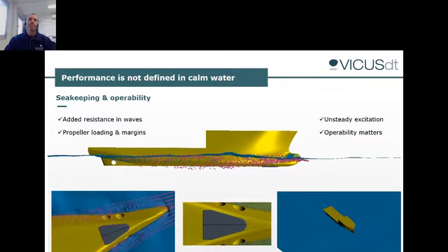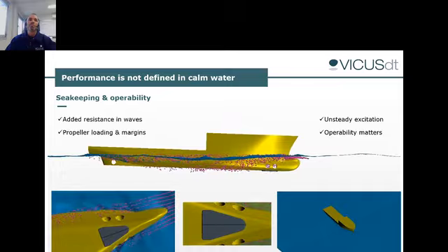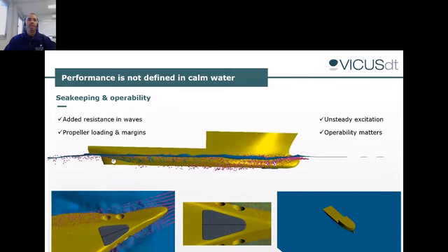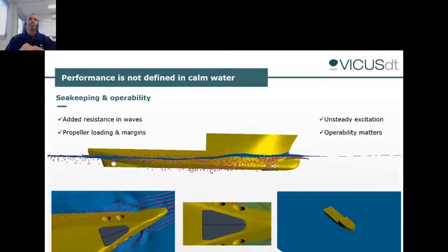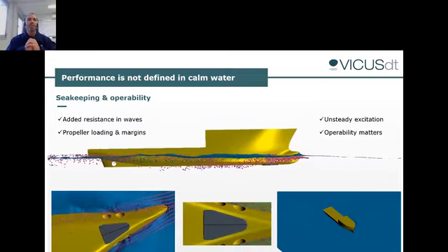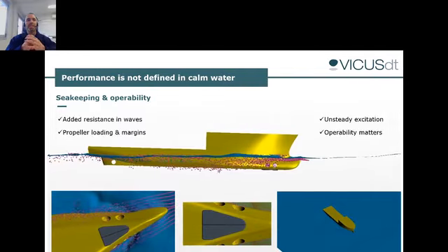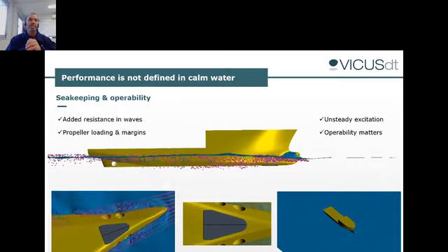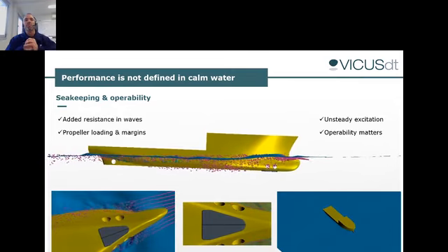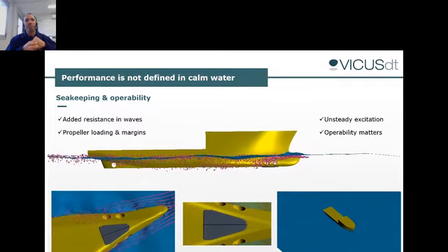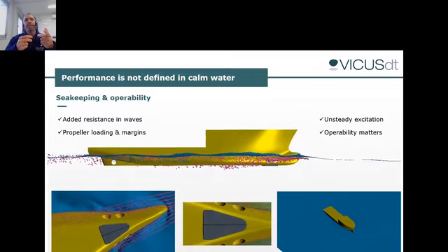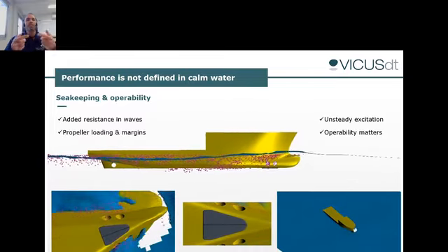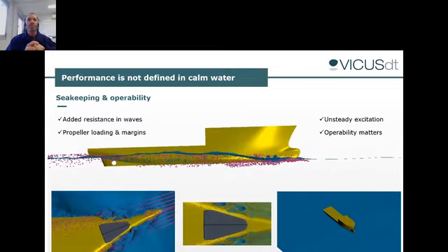So with the CFD, it's quite straightforward to do an analysis on many different scenarios with incoming waves, with the impact it has on the propeller performance, because the added resistance creates an increase on the load on the propeller. And the designer can account for all the margins and take into account, like in this project, which is not for a cargo vessel but an offshore ship, it can analyze even how the breaking wave air bubbles can impact the operation of the transducers in that gondola you can see down there.